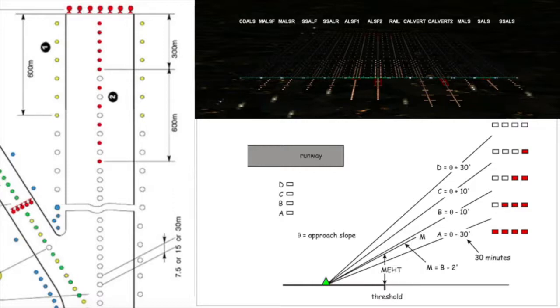Runway status light is also another system, RWSL, which includes runway entrance lights, takeoff hold lights, runway intersection lights, and final approach runway occupancy signals. These lights work in conjunction with different systems and are fully automated. They assist in informing pilots and ground vehicle operators when it is safe to enter or cross a runway.